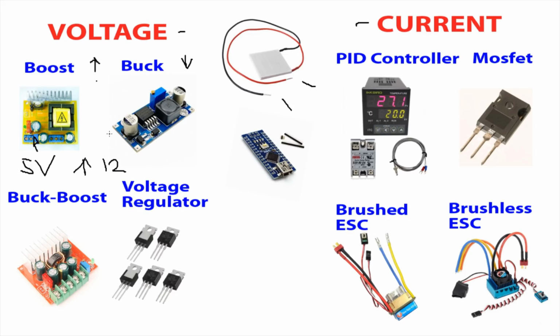Now this could be quite good if you want to increase the voltage because you've got, say, a 24 volt TEC and you've only got a 12 volt input power. So you can then adjust that from approximately 12 to 24 volts, or half the power of the TEC, but you can't turn it off. And a buck is pretty much the inverse of that.